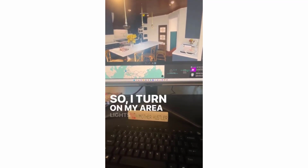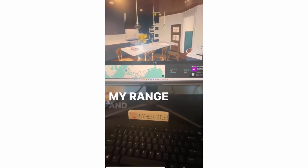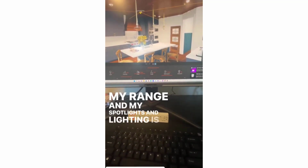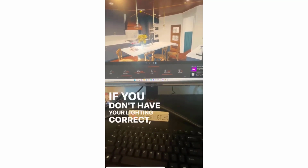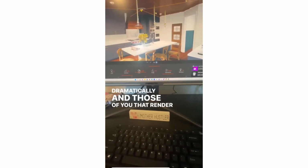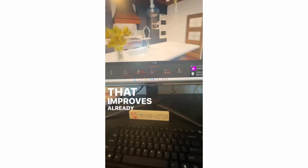So I'll turn on my area lights. And I also add an area light underneath my range. And my spotlights. And lighting is very key when it comes to rendering. If you don't have your lighting correct, your materials are going to suffer dramatically. And those of you that render professionally, you know exactly what I'm talking about. So we have our lighting turned on, and see how much that improves already.